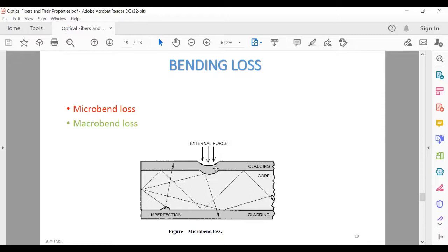Now, fiber sensitivity to bending losses can be reduced. If the refractive index of the core is increased, then fiber sensitivity decreases. Sensitivity also decreases as the diameter of the overall fiber is increased to a certain point. Increases in the fiber core diameter also increase the fiber sensitivity, and fibers with large core size propagate more modes.